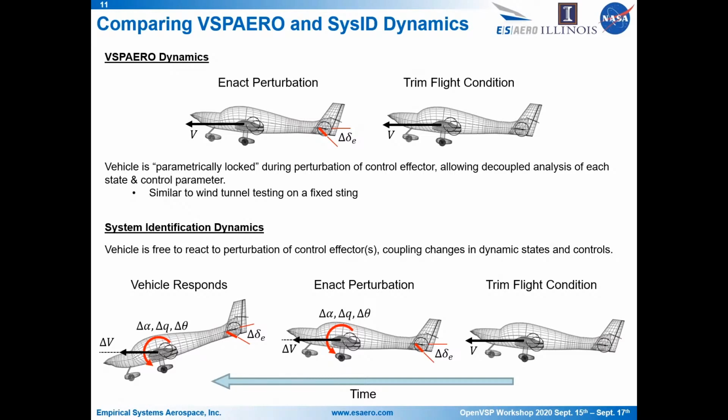And then if you want to look at how forces and moments change with a deflection of the elevator, positive elevator deflection as shown, you can do so while keeping the vehicle parametrically locked so that you're holding all other parameters constant, same airspeed, same angle of attack, etc. And this allows for a more decoupled analysis of each state and control parameter to narrow in on their specific contributions to dynamics.